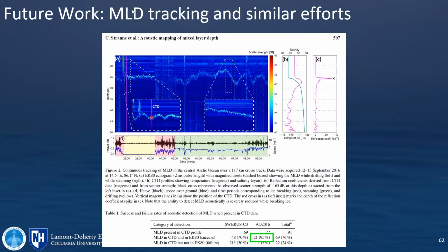So I just really wanted to say I appreciate very much these presentations that were made and the detail in which you've gone into this. I really feel like it's a pretty critical part of getting a system that will work well in a variety of environments. And sound speed is critical, but I also think with these new systems that surface sound speed and decreasing any latency when the system gets that number or series of numbers is crucial, because we did experience some serious artifacts with the system on Atlantis earlier this year. And although the jury is still out, in my opinion, I do think that it has to do with the lack of adequate data update rates or the lack of resolution of the surface sound speed sensor. So I'm grateful that Mac is looking into this and that other folks are paying attention to it.